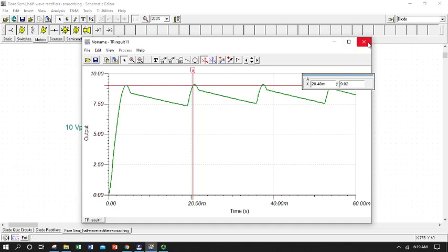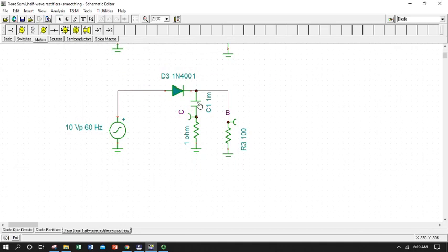If we wanted just true DC, we wanted that ripple to be smaller, we can adjust our tau, our time constant, a little bit more, make it bigger, make this slower to discharge, so we could go with a bigger capacitor. Eventually we're going to reach a limit because the smaller this resistor is, the faster the capacitor can discharge. The two work together, obviously. Tau equals R times C, and our load is usually set by the needs of our external circuit.